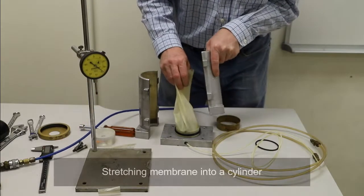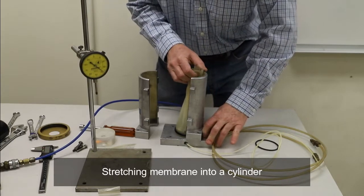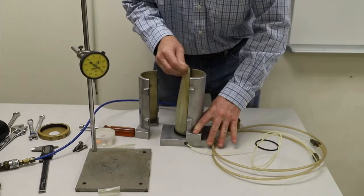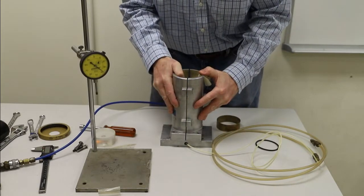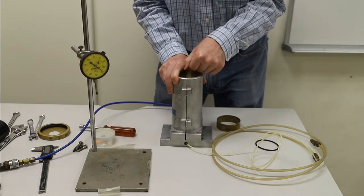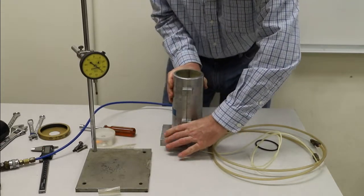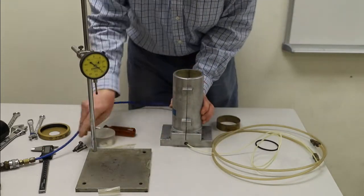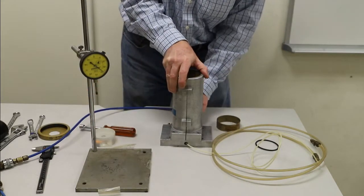So to put this on, we're going to slide this here. Hold it over and down, slip on the other half. I'm pulling up on this while I do this so that I don't pinch the membrane between the 2 halves. And then we have 4 bolts that we need to apply.